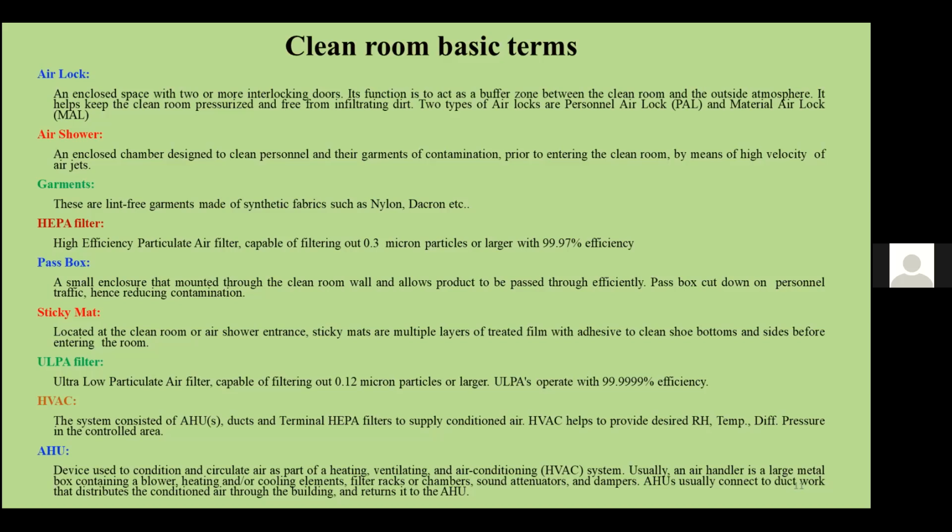So the airlock chamber has an air shower. Actually, everybody goes in our TIFR clean room, I think. So when we wear the clothes and enter that air shower, we close the door and the air shower is started. What happens in that case is that the air shower has some high velocity air, and this high velocity air removes the contamination over the surfaces, means our clean room garment surfaces.